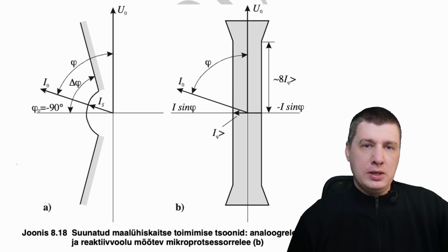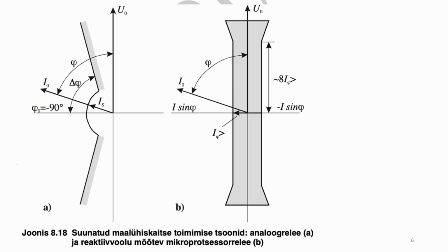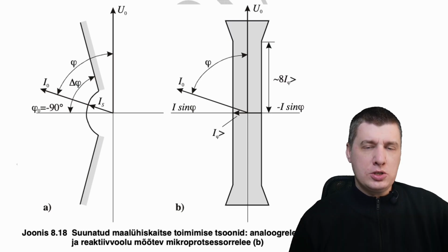Earth fault current can be limited in several ways: by building additional supply substations, by dividing the network into smaller sections, or by using arc suppression coils. Limiting the earth fault currents reduces fault duration, voltage disturbance, and the extent of supply interruptions. Fast and selective earth fault protection further reduces fault clearing time and the number of disconnected consumers. Directional earth fault protection is a critical tool for modern medium voltage networks. It enables fast fault clearing while minimizing unnecessary outages.